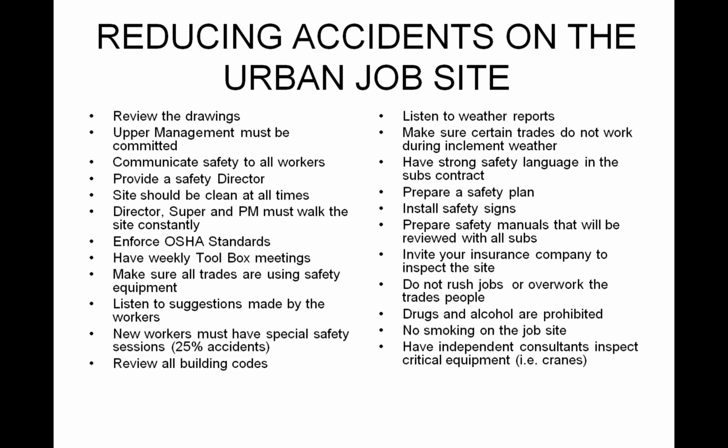Many job sites will have a full-time safety director that goes around just improving work conditions, making sure that everyone's got their own equipment, that all fall protection's in place. One way that you can cut down on a lot of accidents is what we call housekeeping. A very clean site. Everything is organized. Things are piled neatly. If you have bricks, bags of cement, concrete, that they're not just strewn all over the place so that anyone could trip over them and fall and or scrape themselves, bump themselves, whatever the case might be. So having a well laid out site, this goes back to logistics.